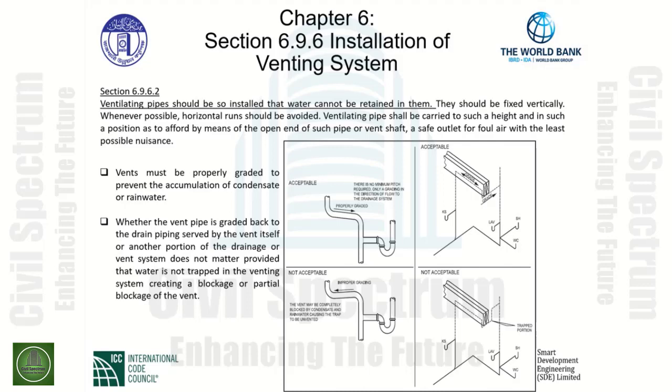What is not acceptable is in the lower right-hand block, described as such. Here is our kitchen sink. We have the dashed line again, which is our individual vent, running across longitudinally with the beam. However, in this case, the vent pipe drops down below the beam, goes across the beam, and then rises up vertically before tying into the lav vent that rises vertically.